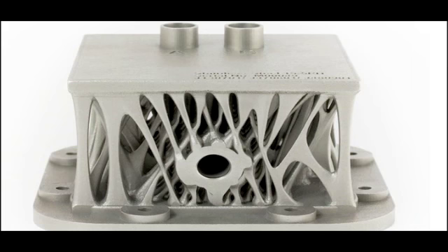Now, in aerospace, they have something called the buy-to-fly ratio. This is typically 10 to 20%. What this means is that they buy this much material, and by the time they chop it off and then mill this bit and add something else and whatever else they do, only 10 to 20% of this actually flies. 80 to 90% of it actually gets chucked away. So this is a lot of wasted material.